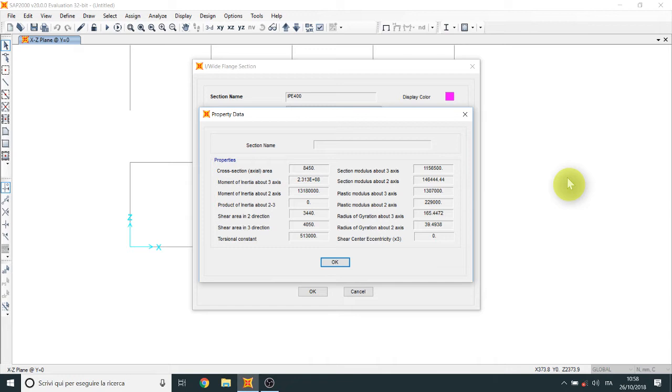I know that the finite element procedure is an approximated procedure. So I want to understand how many finite elements I need to obtain these results. And what is the error if I'm using only one element? In this special case, I expect that with one element, I must obtain the exact result, because the shape functions are of the same degree as the solution. So I must obtain the exact value with my finite element software, in this case, with one element. I don't need to refine the mesh. This is what I expected.